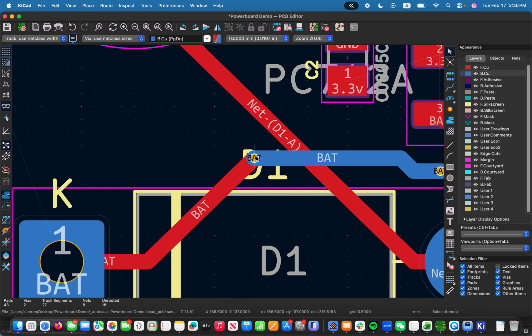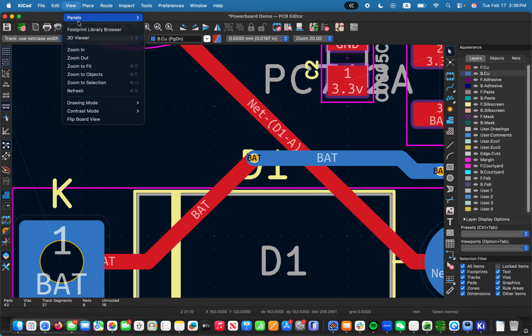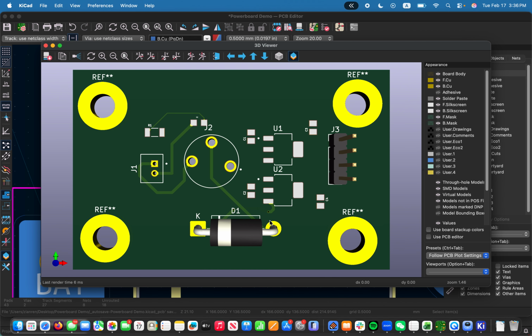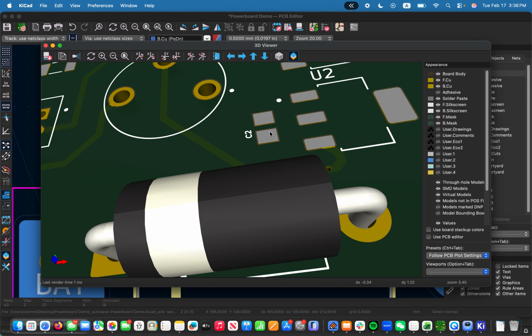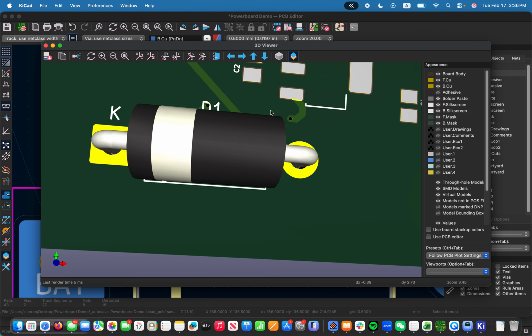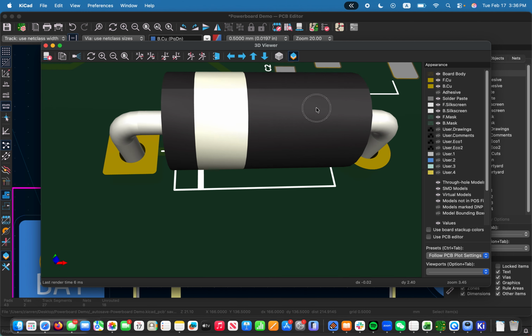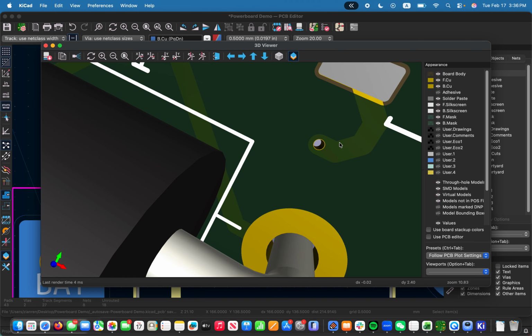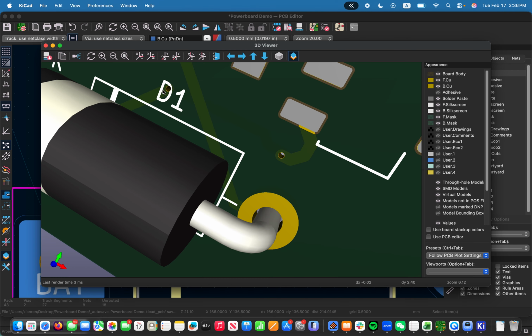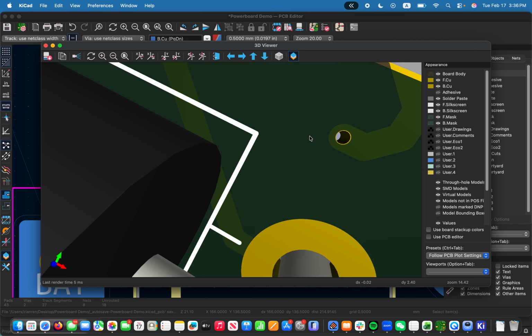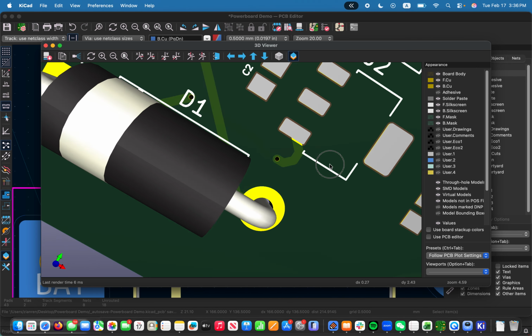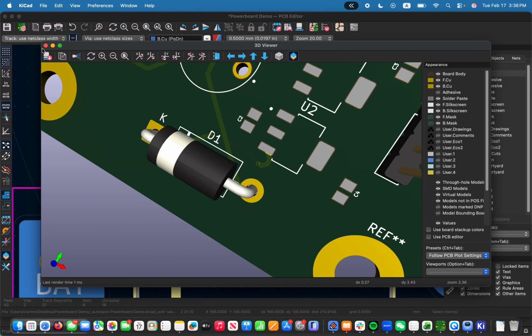But basically what the via is, if I look at the 3D view, the via itself, oh, you see, we can see those holes. So if you use your middle mouse button, you can move around, and then use your left mouse button to rotate in the 3D viewer. So those are my vias. The via is basically a hole that lets electricity flow from the top side to the bottom side. So make sure you don't solder those holes in. That would cause a short if you have maybe a ground polygon layer.